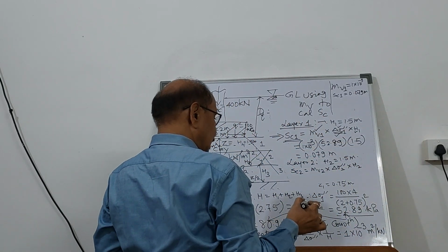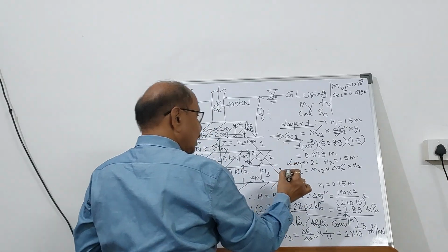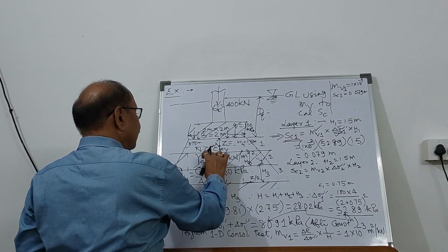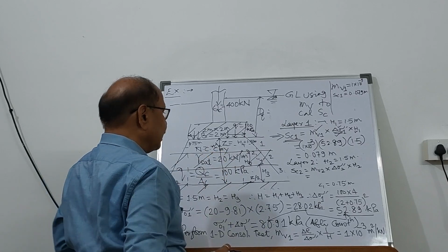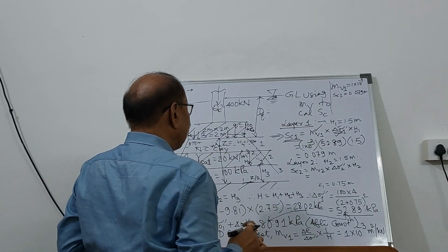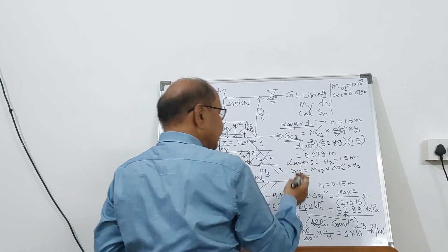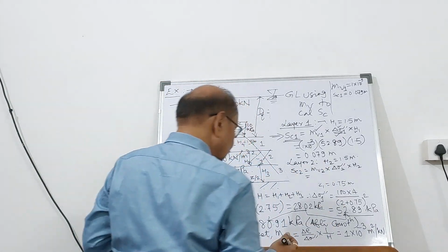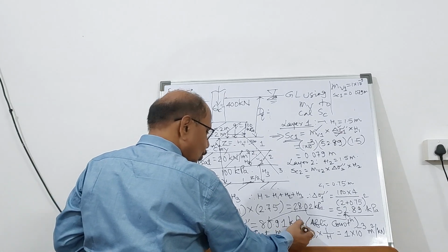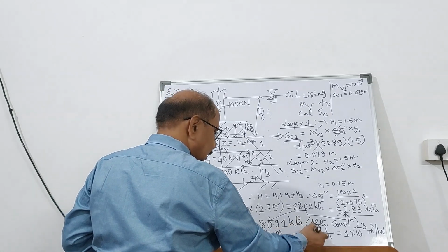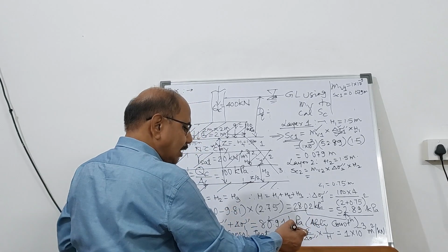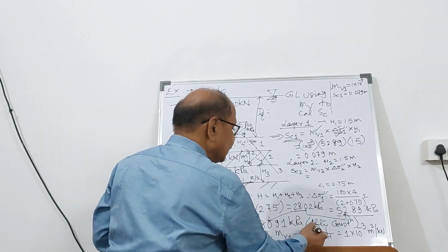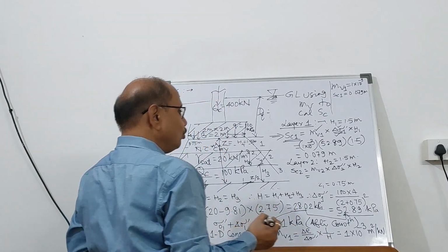Now, MV2, I have collected the sample from this layer and I can find out the value of MV2 by knowing the change in void ratio while performing the 1D consolidation test, and how to find out this delta sigma 2 prime.